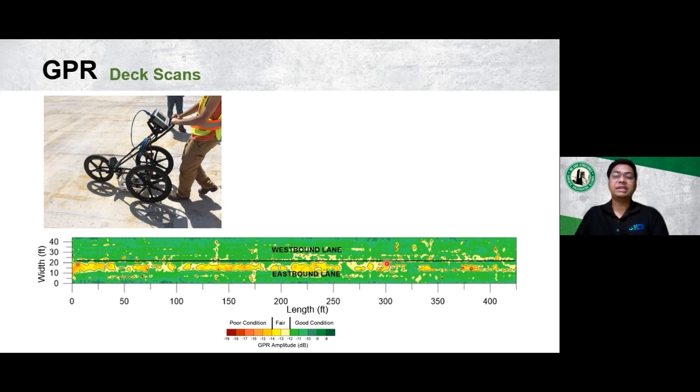And the areas of high signal attenuation indicate locations of probable concern, indicating potential contamination or deterioration. This deterioration could be a high concentration of chlorides or moisture, which could lead to corrosion, or it could be corrosion activity and concrete cracking. The difference between these states cannot be discerned by the GPR, however.